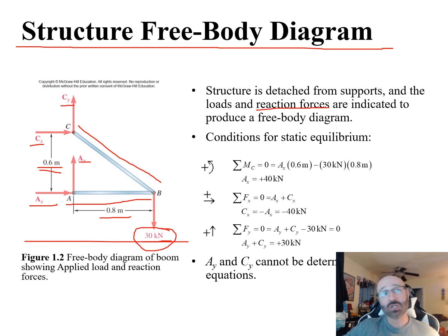Now, as I'd mentioned, you don't necessarily need to do these all in one. You can do out 2 separate free body diagrams as well. Pros and cons to both. A little bit more work, a little bit more drawing, draw out 2 free body diagrams, but it's a little less congested, easier to follow, especially as we get complicated. There's 5, 6, 7, 8, 9, 10 different members within a truss problem like this. You might want to break things down into individual free body diagrams for that.